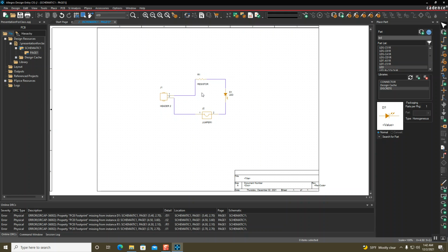One of the things to watch out for that some people sometimes do is they will place a line. A line is not an electrical connection, and to show that, we're just going to delete this and then place this line. And it looks like it might work, but what you see is that there is this square at the end of the component. When the square is open, it means that there is no electrical connection there, and you're going to get errors when you try to export this. So delete lines and place wire. And that's our schematic.